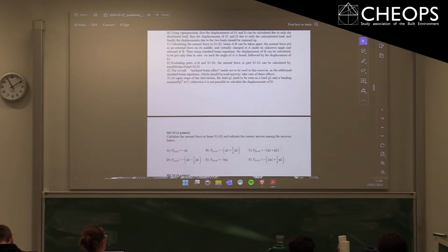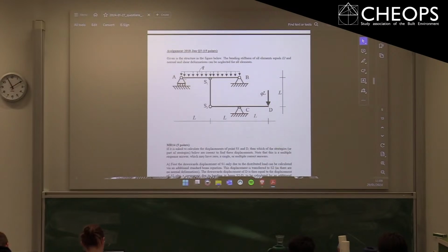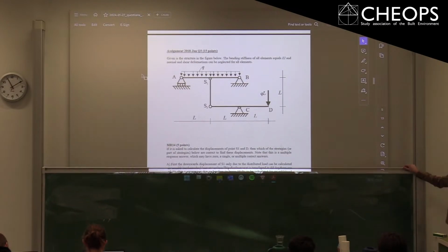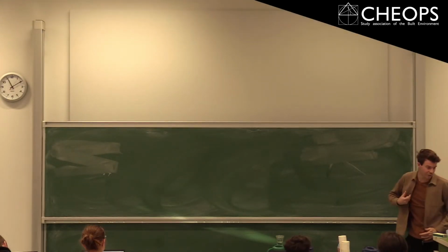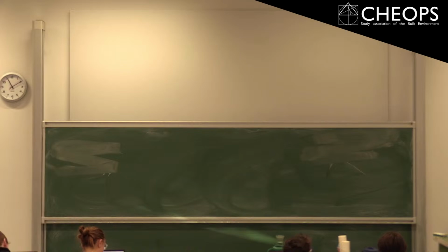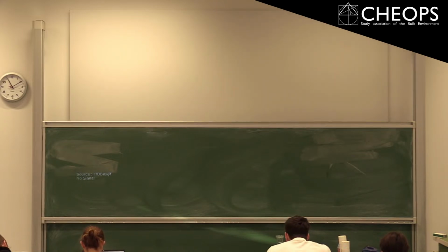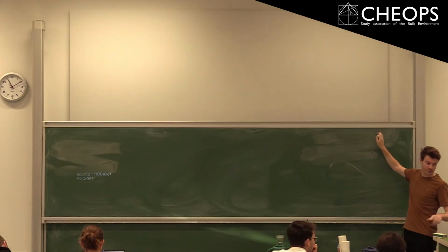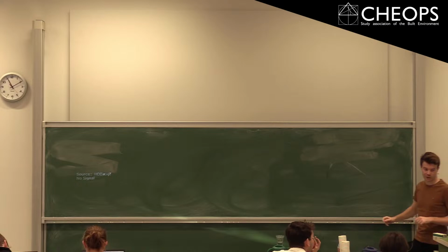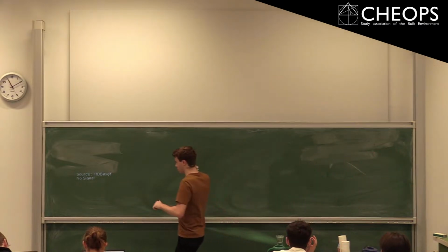And then what they asked is first the normal force in the beam. So I'm going to put this on the blackboard. The normal force in that beam, you can actually calculate by statics. So you have to draw your free body diagrams with all the internal forces. And what we're going to do is use the bottom segment of the structure, because at the top you cannot really use it, as there you will have too many unknowns.